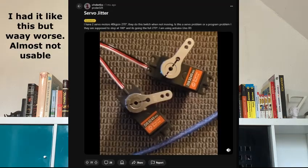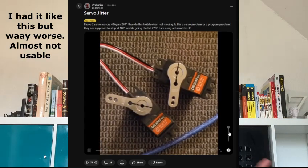Biggest thing of all, servo jitter. Still can't fix it, still don't know what causes it. The servos have Parkinson's, and I don't know how to cure them. Neither does medicine. I tried a different power supply, more voltage, more amps, putting capacitors in there to smooth out the voltage, because maybe the power supply sucks a little bit. Different Arduino, better code, different servos, everything. There are no more problems. It could be in a wire, maybe 5G towers.